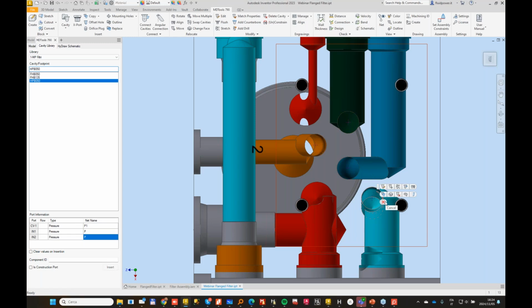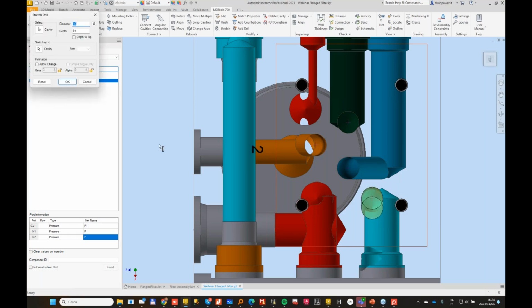If you have a 5-axis machine, perfect, but if you have just a 4-axis machine, this will require a new setup. So it's always better to have all the inclinations going in the same direction. Plus or minus is not usually a problem, but it's better not to have different directions for drills.